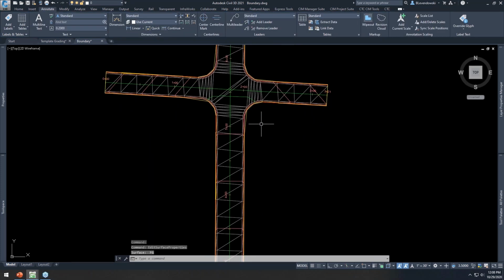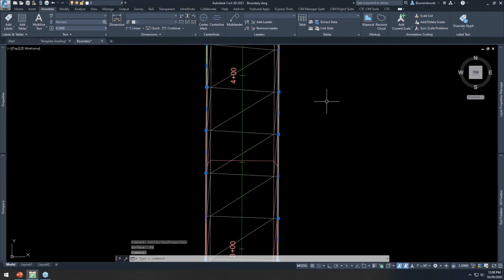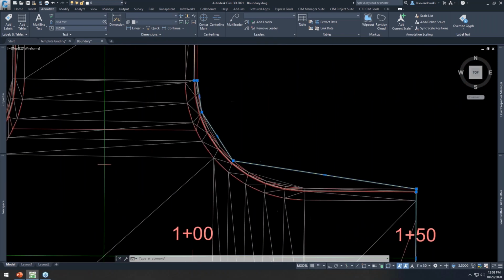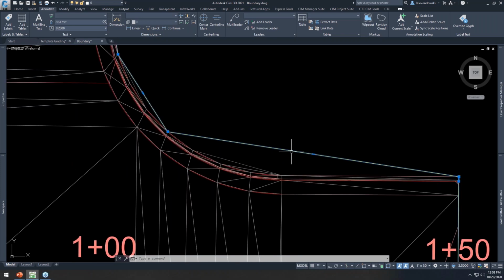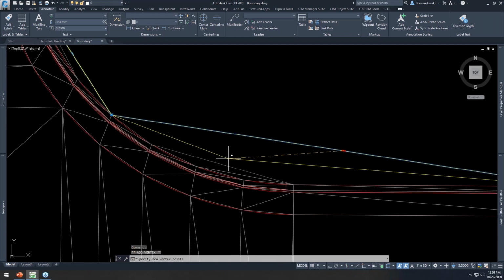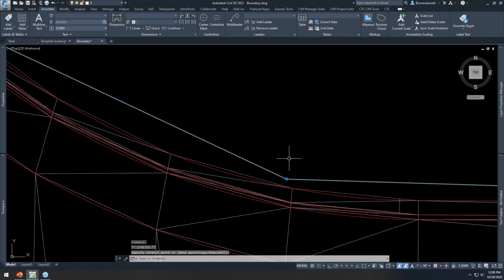Now what we've done to create this is generate a simple 2D polyline, so that if it doesn't trim exactly how you like it, you can adjust it. We had to be very careful with how this creates a boundary. We don't want to eliminate geometry in your surface that you do want there, but sometimes there might be a little thing like this. What we've done is create what's called a non-destructive boundary, where we've unchecked that option when creating this boundary. And with a 2D polyline, you get this really handy add vertex operation. If you simply run that, you can very quickly and easily trim out these excess triangles, okay?